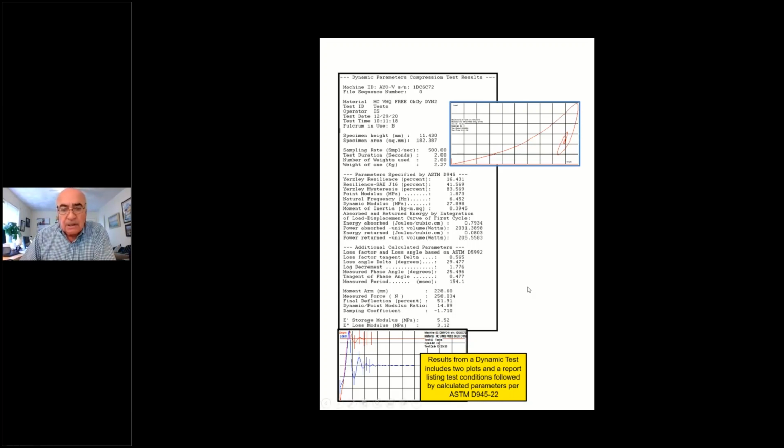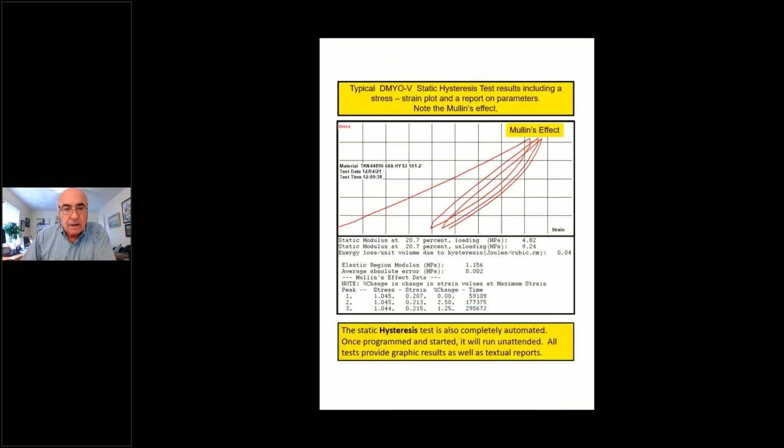Then we go to the next test, which is, sorry, okay, finally. Okay, this is called static hysteresis test, which really is, as we go back to the table, the moving table, we can initiate that motion, say, between 0.1 inch and 1 inch increments, meaning the table moves and stops for a second or 5 seconds or whatever you choose.